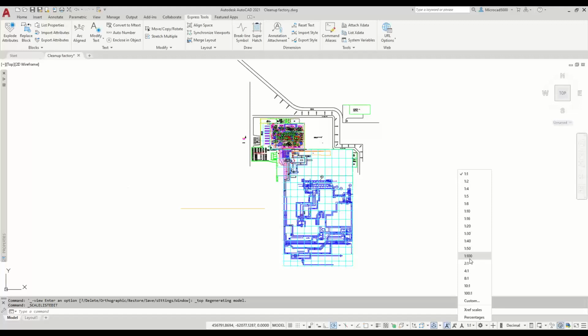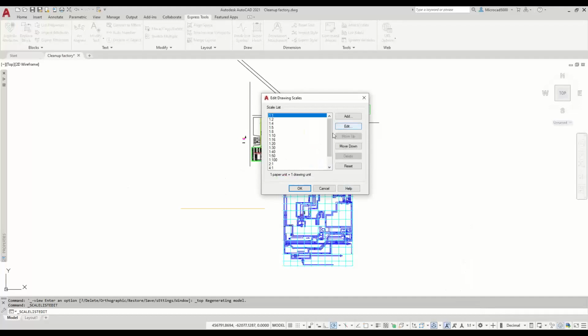If you're surveying tracts of land or anything else, and there are some scales in there that I don't want either. 1-to-16, 1-to-8. I don't want those. I want proper standard metric ISO scales. Now I could go back in here again and pick on the edit button.